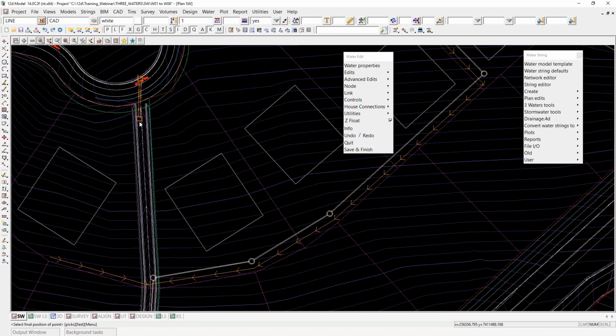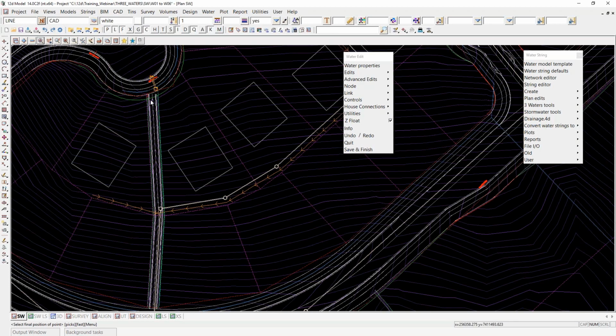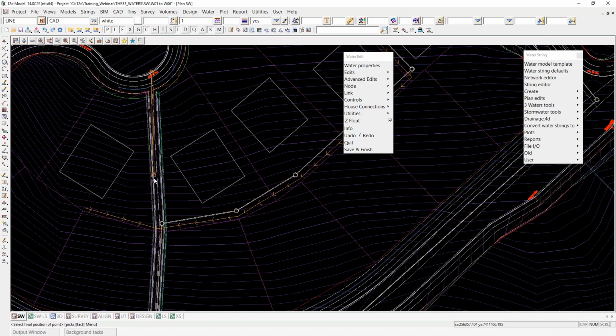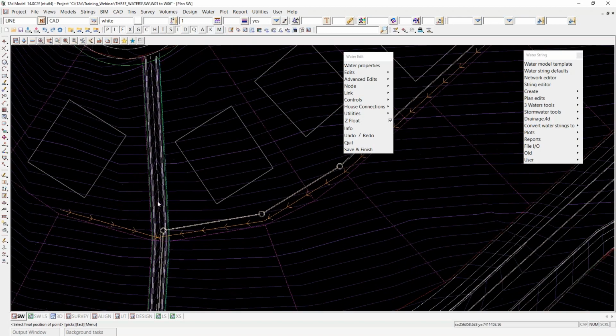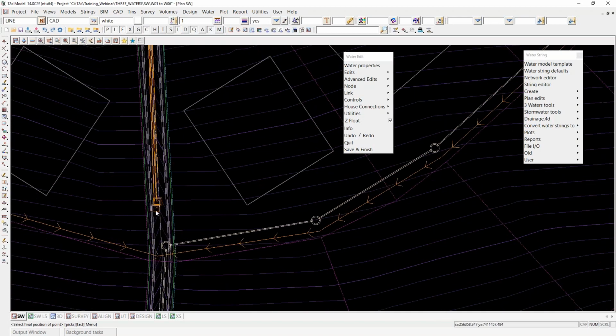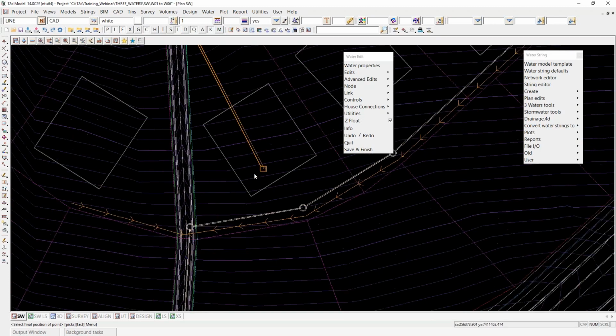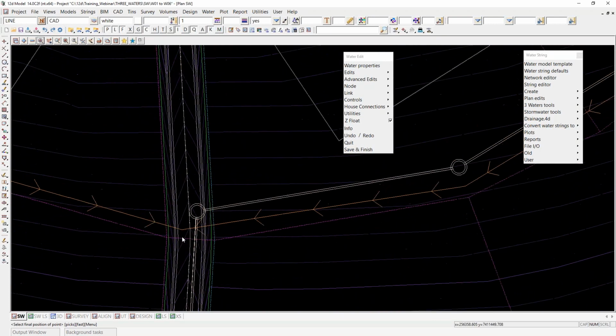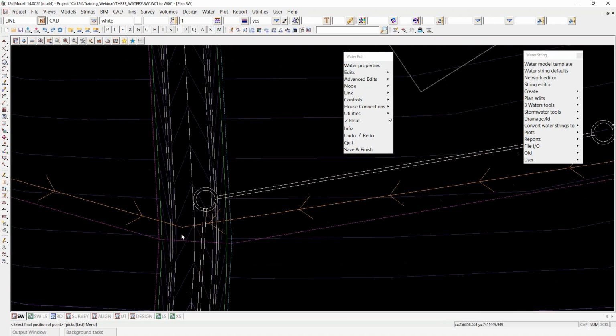Moving downstream then, I want to go down the middle of, well, somewhere down within the easement here between the 2 dashed lines we can see. And I'm also being careful to avoid the sewer line here, which is a proposed sewer line that is in parts running parallel to my stormwater network.